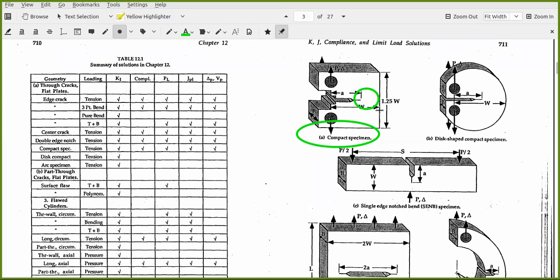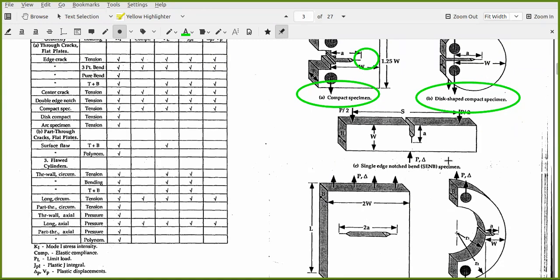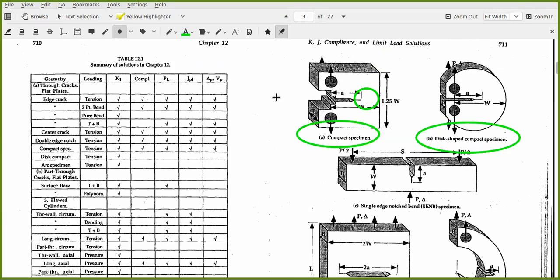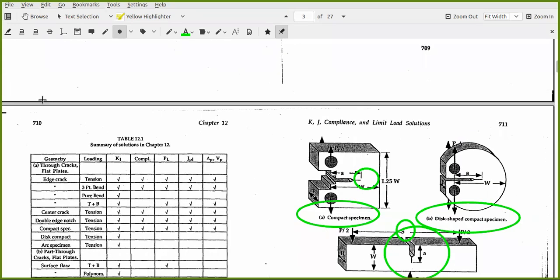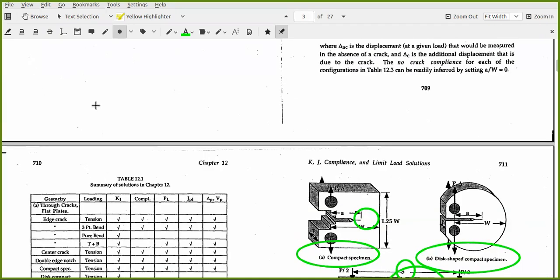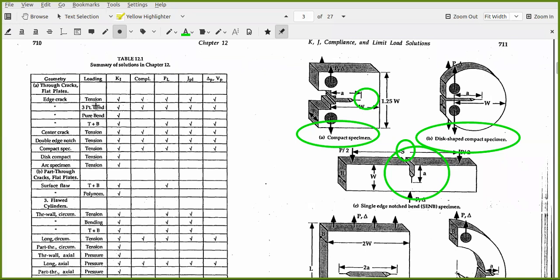What's the stress intensity factor here? This compact specimen is produced from cylindrical specimens used in fracture toughness testing of different types of materials. Then the bend specimen, simply the 3-point bend specimen, or here it's referred to as a single edge notched bend specimen. You can see the details regarding the geometry, and crack length is a. What's the stress intensity factor for this case? These do not lend themselves to analytical solutions. Analytical solution is not possible. Numerical, three-dimensional, and computational analysis are required.